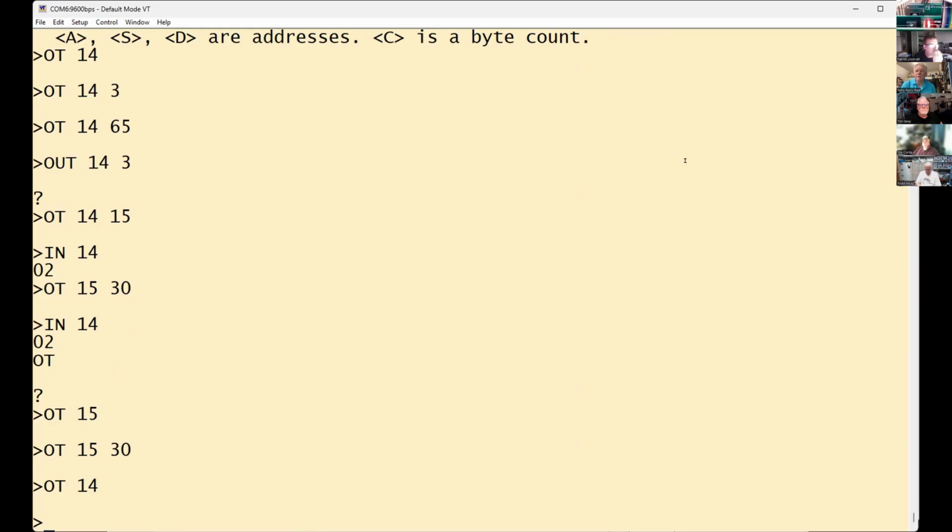He's on what, 14? So that'd be port 1 of this board. That looks odd to me. If you have transmit looped into receive data, you'd think your LEDs wouldn't be two different colors. Oh, there we go. It's like transmit was connected to ground or plus 12 or something.